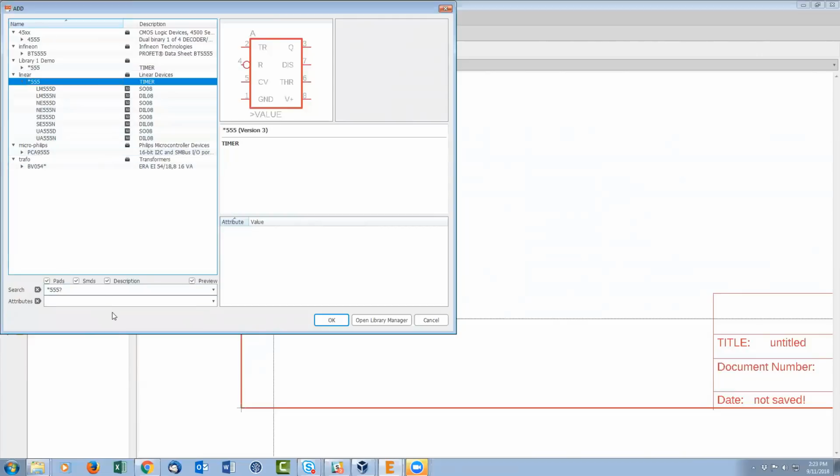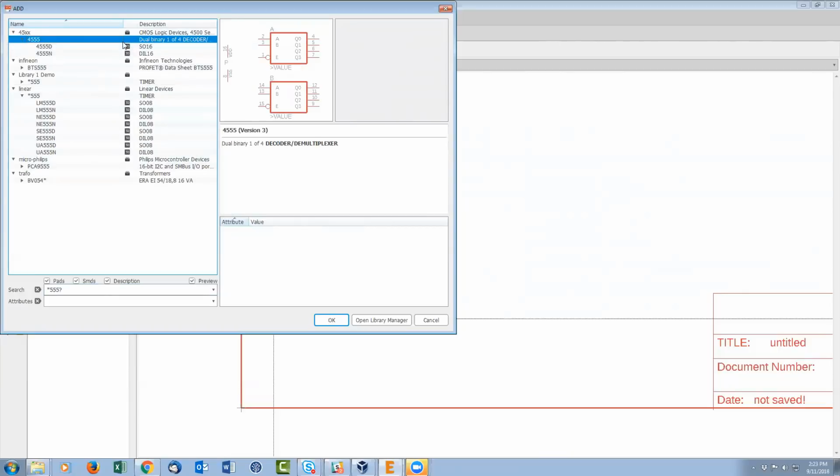So what's the key takeaway here? If you want to have the best chance of finding the part that you're looking for, just use asterisk. Asterisk is the most flexible, the most generic wildcard. It will give you the most results. Some of them, you know, you don't need. Like, obviously, I'm not looking for this 1 to 4 decoder. It's not what I'm looking for. But in that generalness, it did find these. And this is something that we want to make more Google-like as time goes on, so that it's easier for users to find the parts they're looking for.